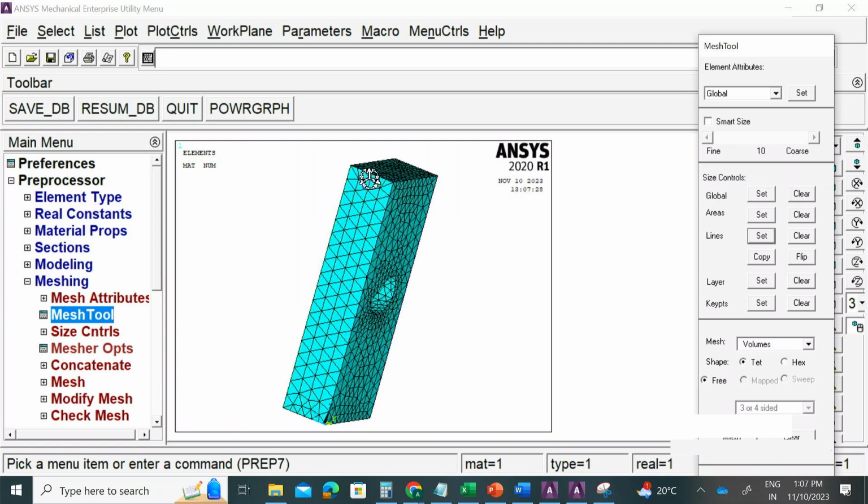So dividing this by 6 points is actually causing the elements to increase in certain places. So the aspect ratio which we talk about is very important. So we should not divide a small edge by a very high number of divisions and the longer edge also by the same number of divisions. That's why we are getting the warnings, right?